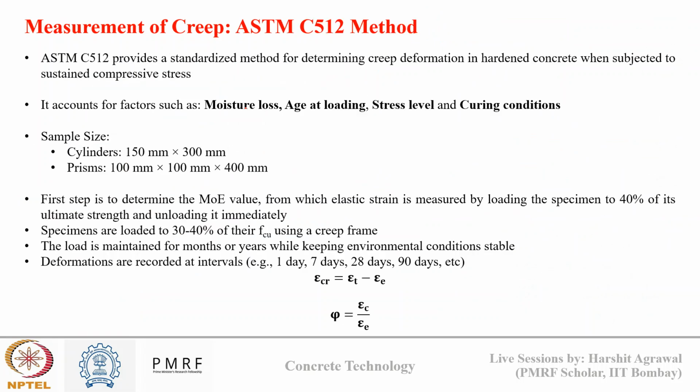Now, how do we measure creep? That was prediction, where we know for how much time we are loading concrete and what the creep can be in future. But suppose now on site or in the lab I want to actually measure creep. For that there is the ASTM C512 method. It accounts for moisture loss, age of loading, stress level, and curing condition for determining creep.